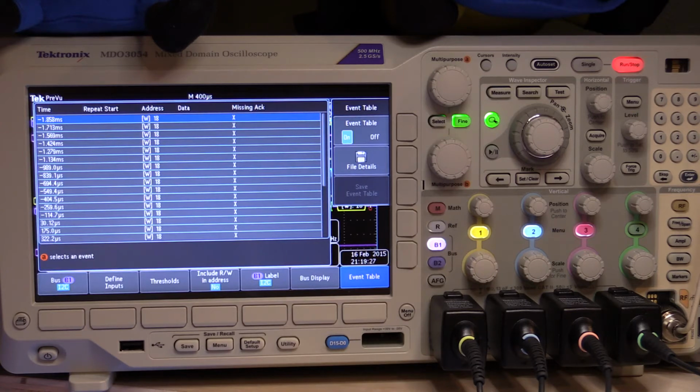So if I just change this in my code now, all right, 4C, when it shifts left 1 bit, gives you 98. If you don't believe me, bring up a hex calculator or write it down and you will see. Anyway, I'm just going to enable this in the code. So you can see how useful it is to have something that can actually do protocol decoding. That very quickly showed us that even though the Texas Instruments code was using address 98, with the Arduino libraries, the way that they're coded, they're actually only allowing the addresses to be the lower 7 bits of the address, and they're actually shifting them when they're putting them out on the bus, which means you're losing the most significant bit. Alright, I've just changed that code now.